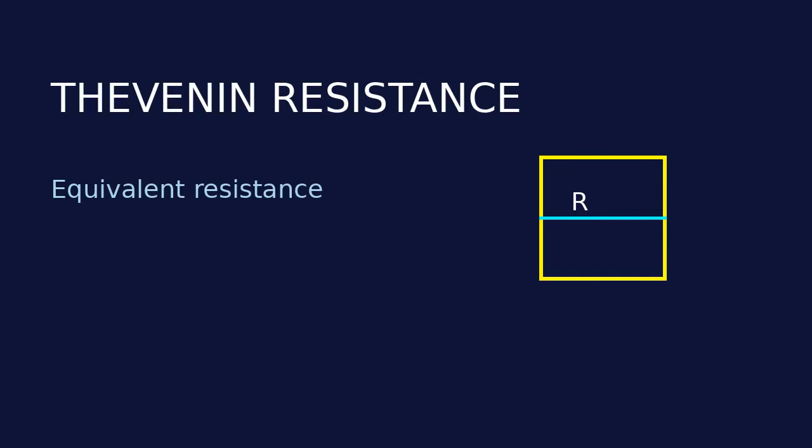A concrete example with two voltage sources. Calculate VTH between A and B with no load. First, only V1 active, V2 shorted, with A and B open, no current through R2. Let's simplify.